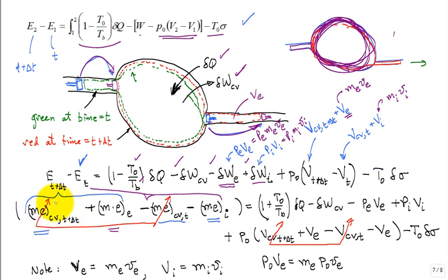Now at this point, these two terms over here with the red, I'm showing you something that cancels right away because we're assuming steady state. Otherwise, it takes a lot more tediousness. It takes me 2 pages, 3 pages to do it. Likewise, the volume of the control volume doesn't change. This control volume doesn't change. So this red strike, those two terms, greatly simplifies the math if we assume steady state right there.